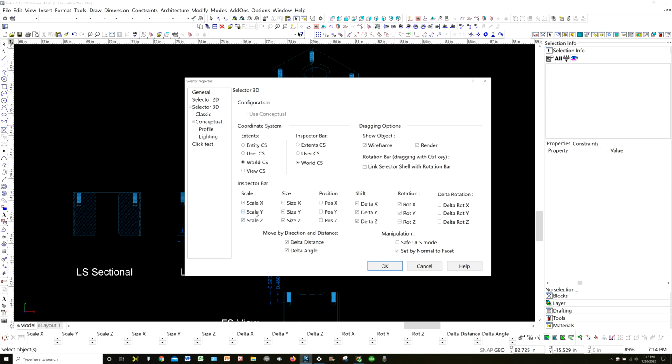But what I do use a lot is scale. When do I use scale? Let's say I'm importing a 3D bolt. I went to McMaster-Carr and brought in a 3D bolt, and my units are all English in inches, but the bolt is metric. I'm going to have to scale it so that it's right. So what do I multiply it by?